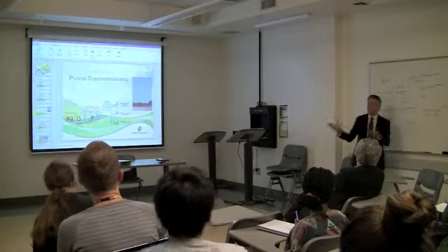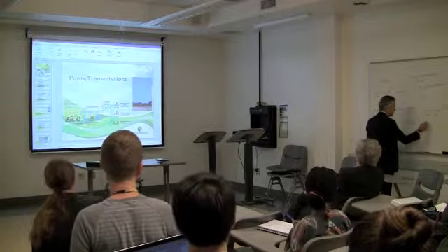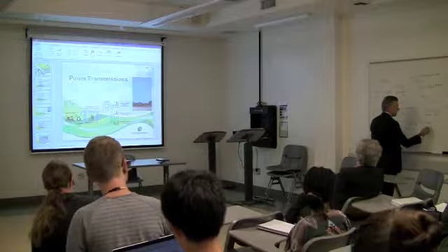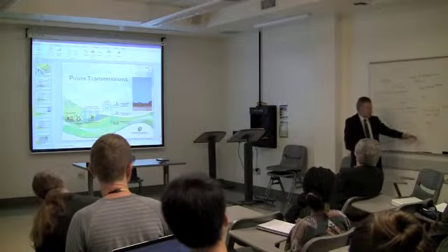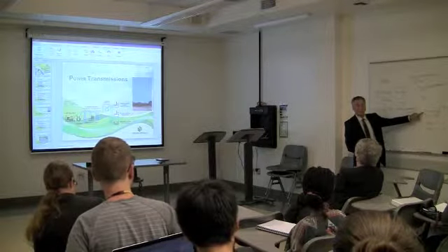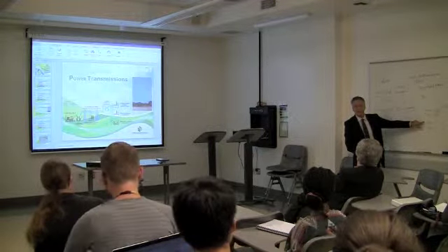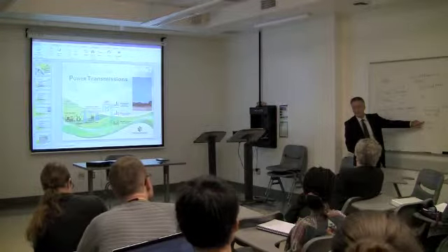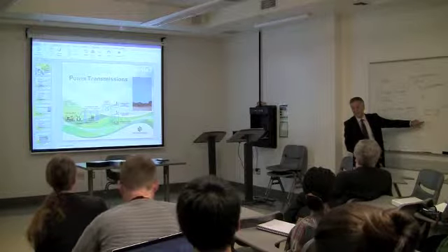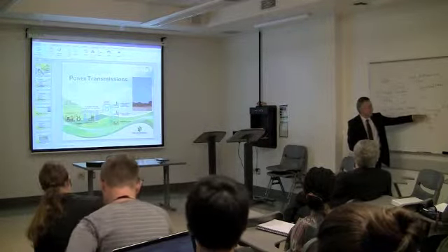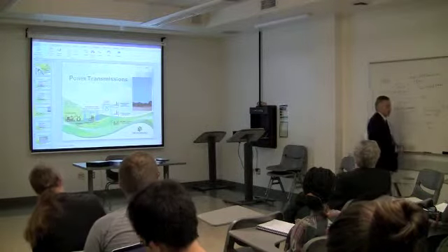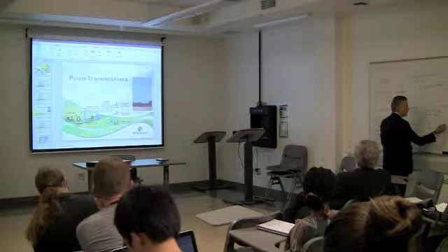What we use here is 110 volts, and the amperage for this room is 30 amps. So compare these with those numbers. If you had that much power coming to this room, everything in this room would be melted. All your computers, the light fixtures, everything. And it would catch fire. So the way we do it is, this comes to a huge station, and then there's a device called a transformer.